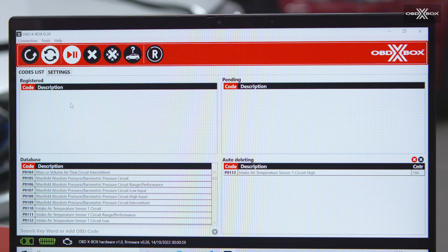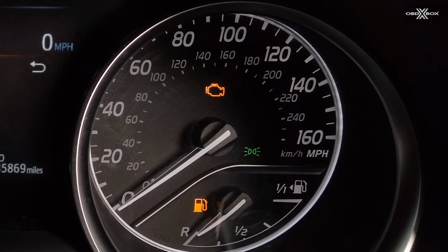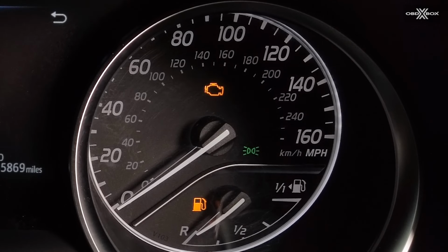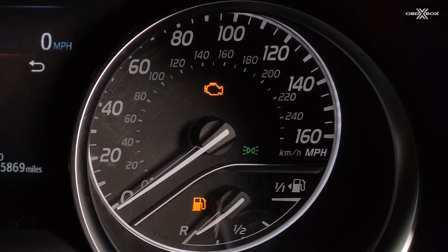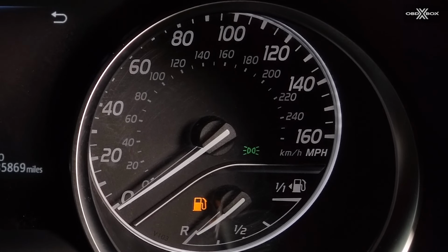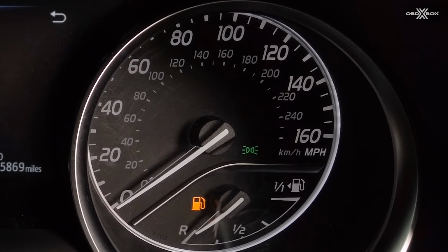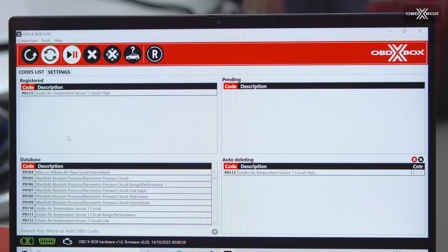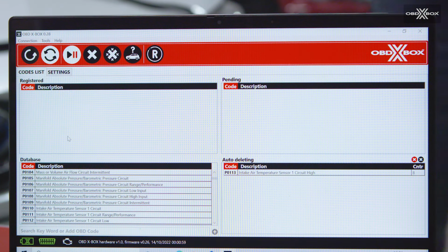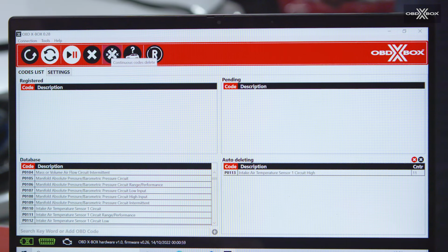This read, check, delete takes some time, and even though the delete time may be very low to delete quickly, you may sometimes see the engine management light flicker on and off because the loop isn't as fast as the refresh. If the read, check and delete mode is not fast enough, then it's possible to use the continuous delete button.